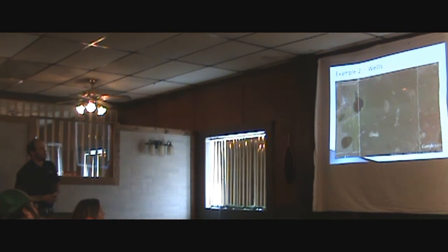You can't really see it that well, but it picked up another 50 acres up here. So basically, the variable rate system allows you to cut your horsepower requirements, because you're turning these pumps off during the year, you're picking up more acres, you're saving water to possibly use elsewhere, so it's really several advantages of doing it in that capacity.